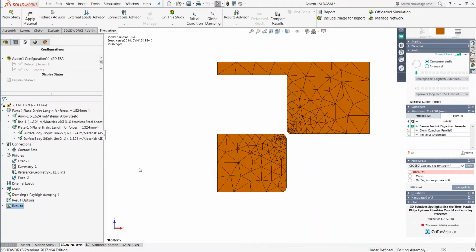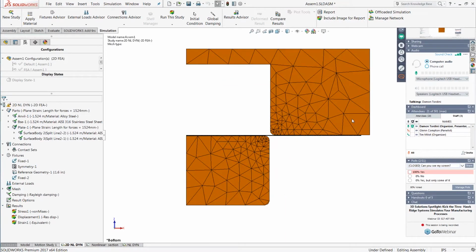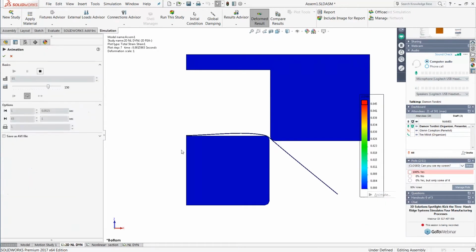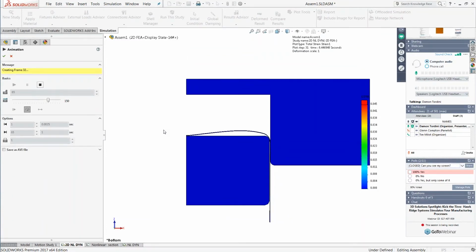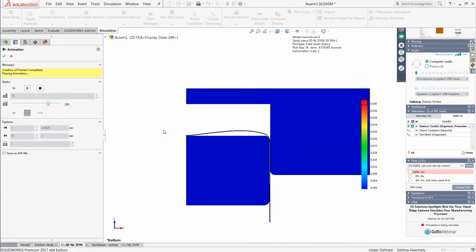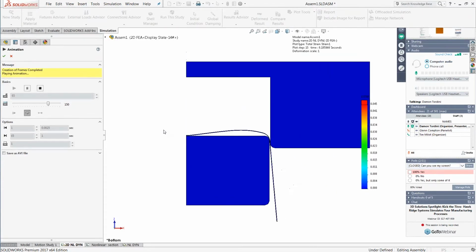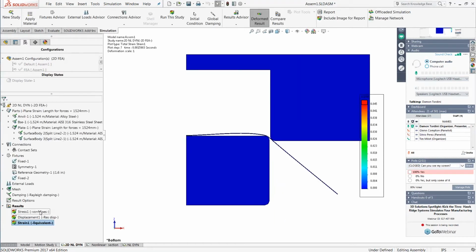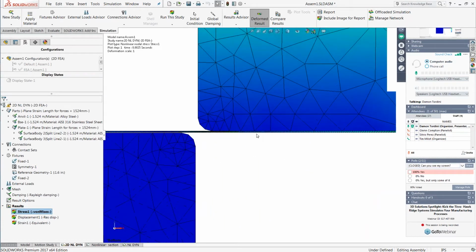Looks like it did, and of course it would do all its calculation steps that are necessary to see what the stress and strain and displacement are at all these different stages as the die is moving down, and of course we'd be left with an animation, as well as all the numerical results about what's happening during this process. So we can see there the channel mostly gets formed at the beginning, and then as you would expect, stresses are developed over time.